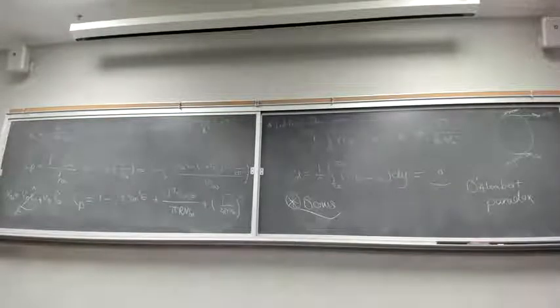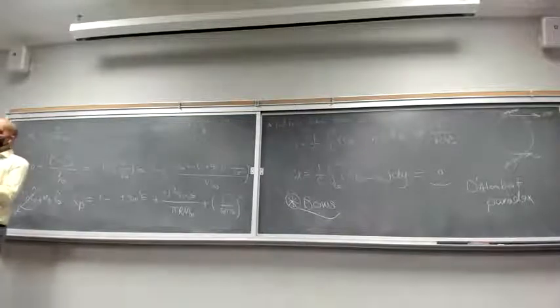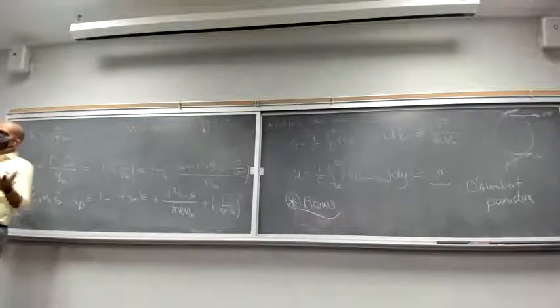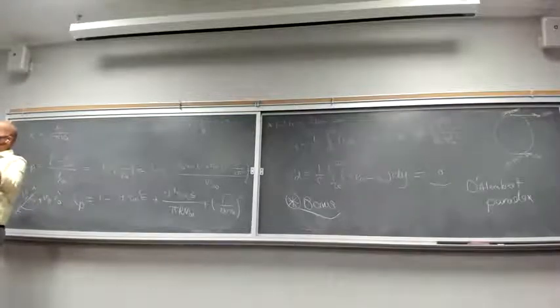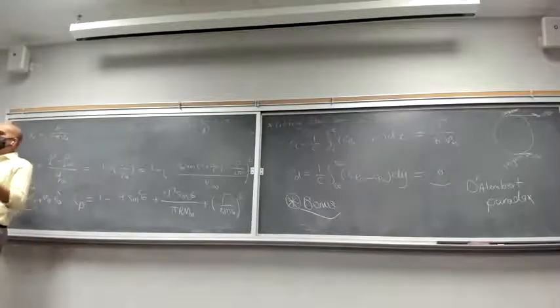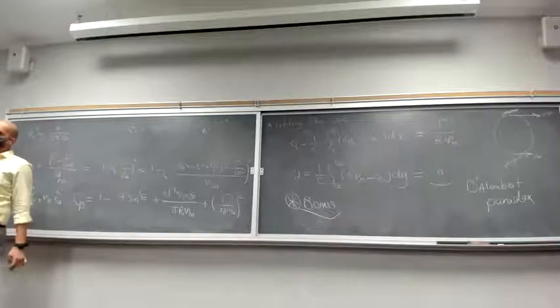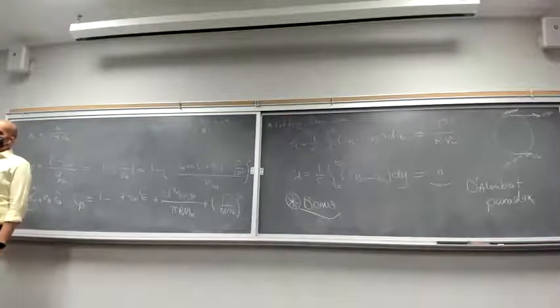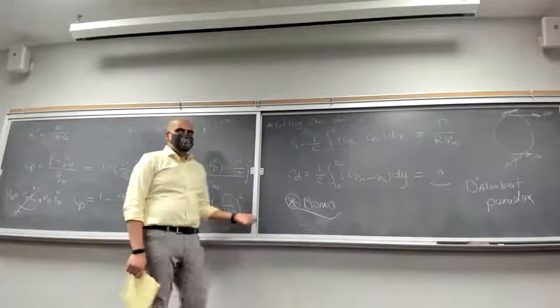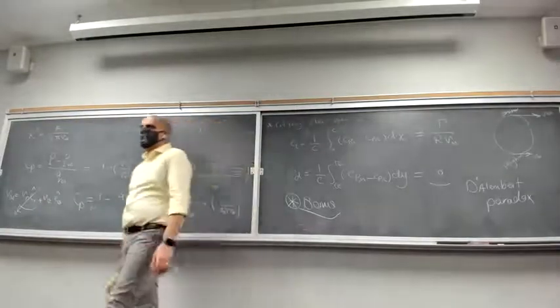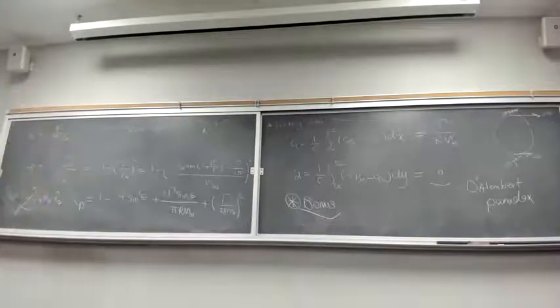The reason we get lift, as Paul asked in the previous class, is actually because of friction. From a physical perspective, if we didn't have friction, we wouldn't have lift. But the amount of lift is due to the pressure difference on top and the bottom. As long as you can calculate that pressure difference, you should be able to get the lift coefficient. But most of the drag is due to friction, and we are neglecting friction, so we are essentially not seeing it.